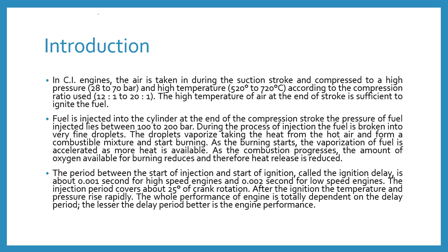So students, in the CI engine, the compression ignition engine, the air is taken during the suction stroke and compressed to a high pressure of about 28 to 70 bar at a high temperature. That range is 520 degrees Celsius to 720 degrees Celsius according to the compression ratio used, from 12:1 to 20:1.